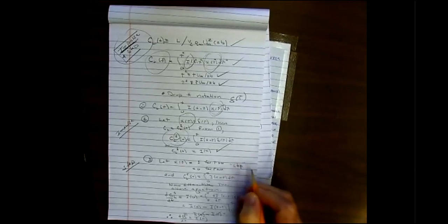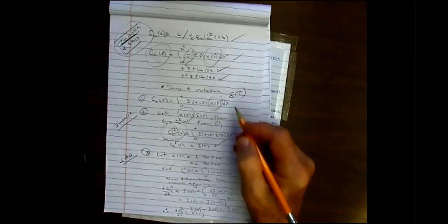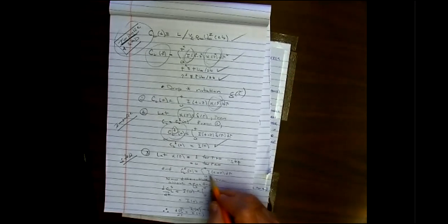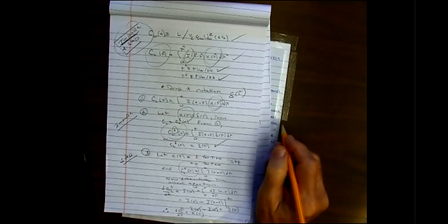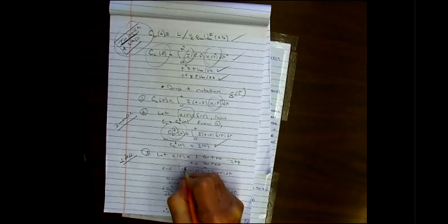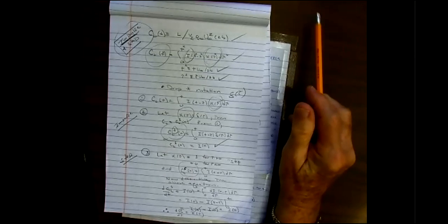computationally and certainly experimentally. Okay, well, if that's the case, if I put a step in, then this wonderful equation I have up here now becomes this. I don't have I right away. I have the integral from 0 to t of I of t minus tau d tau. And that's related to the lift coefficient due to a step. And I put the S up here to remind myself that this is not any old lift coefficient, but a lift coefficient due to a step.